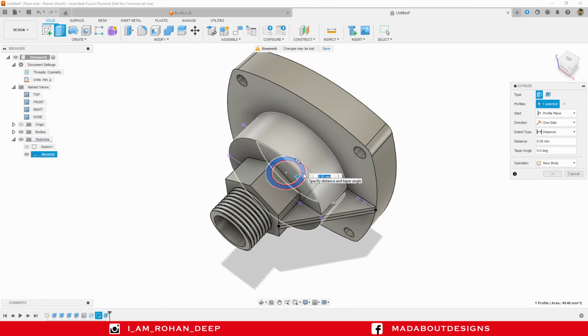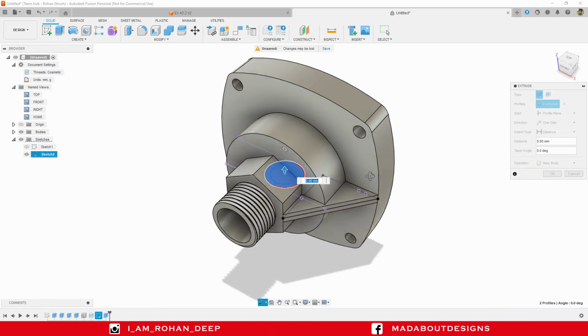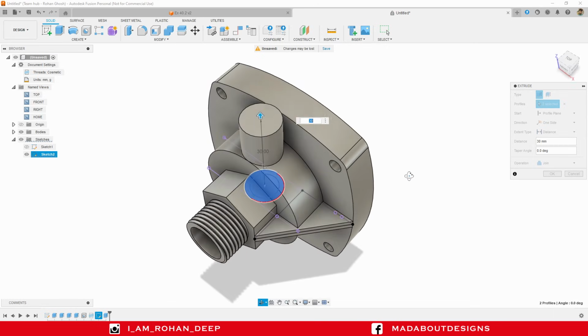So click on this and also the inner profile. Extrude it up to 30 mm. Change the operation to join and click OK.